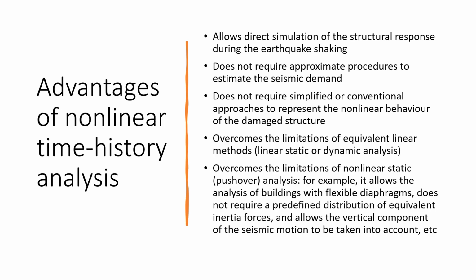It overcomes the limitations of equivalent linear methods and overcomes the limitations of nonlinear static pushover analysis, which are less relevant with respect to the linear methods, but in some cases relevant. So for instance, it allows for the analysis of buildings with flexible diaphragms without any need for specific simplification.